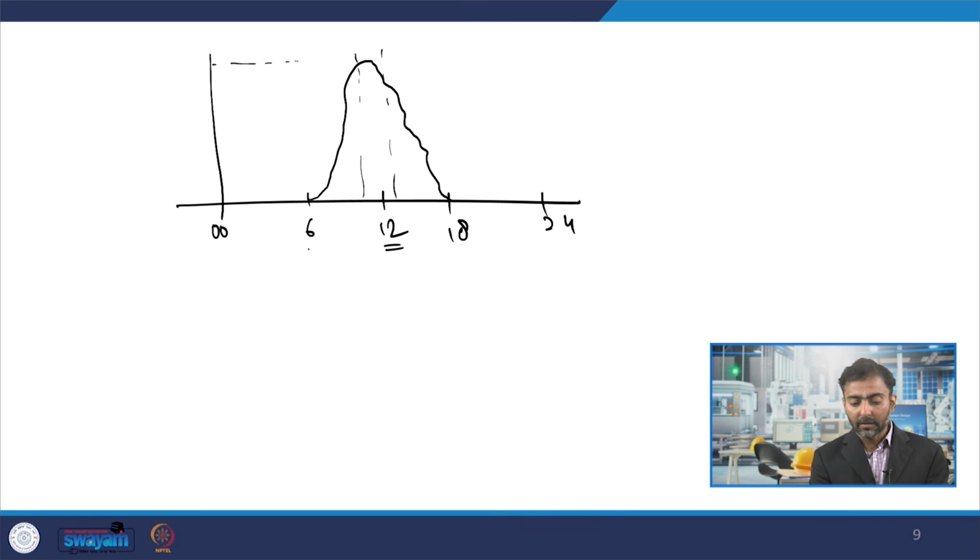So if you see, that is where it is actually running at its installed capacity, and that too it will run at its installed capacity only when the solar radiation, which we will be looking at in more detail in the later classes, but just to tell you, if the radiation is around 1000 watt per meter square, then it will run at its rated capacity. On some days when the solar radiation is lower, then it might peak only at 400, 500, 600, that type of peak.